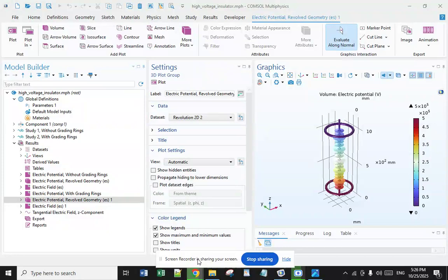And what about maintenance and testing? Maintenance of suspension insulators involves regular visual inspections, cleaning to remove contaminants that may compromise their performance, and electrical testing to assess their condition. Testing may include measuring insulation resistance and verifying the mechanical integrity of the assemblies.